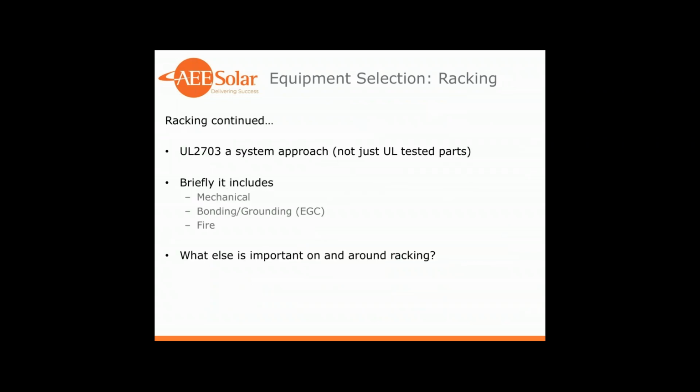So just a quick review on the UL 2703 standard. It used to be that you tested your racking components individually to different UL standards. A ground lug would meet XYZ standard, the rail piece would meet a load standard, and now 2703 has changed it to a complete system.